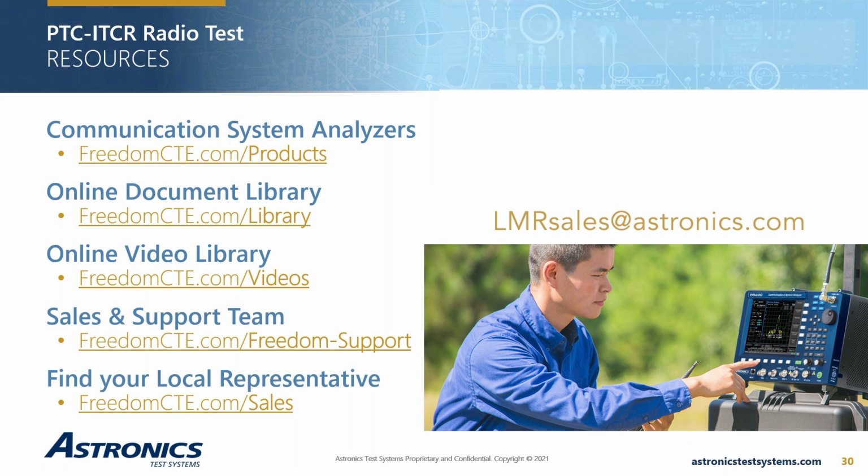Now is a great time to find out if there are any questions we can answer for you. Let me switch over to my question screen. I've got one question here that asks, what is the overall frequency range? The PTC itself is 217 to 222 megahertz, but if you're asking about our instrument, it's capable of 250 kilohertz up to either 1 gigahertz or 3 gigahertz. 1 gigahertz is the default, and then there's an option. Every instrument that we sell is calibrated to 3 gigahertz, but to operate above 1 gigahertz, you do have to have that optional 3 gigahertz option. And then peak modulation gate time is the other part of the question.